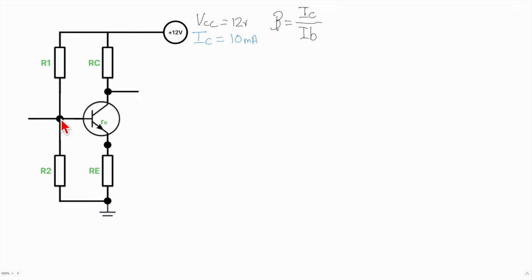And you say, well, where's the extra one come from? Well, the extra one is the original base current, because remember, the current is flowing from the base to the emitter. So we might have 100 times here. We've got the same there, plus the original current flowing through. So that's why you've got slightly more current at the emitter than you have at the collector. But for all intents and purposes, the current on the collector is practically identical to the current on the emitter.